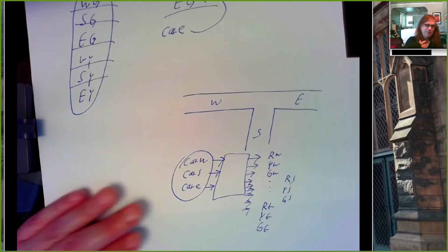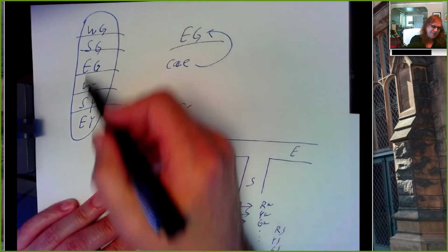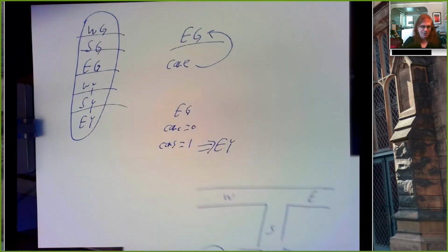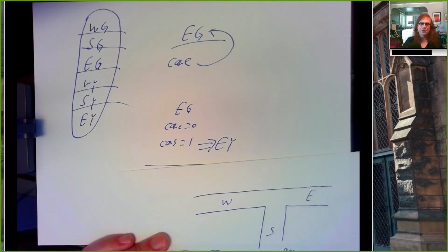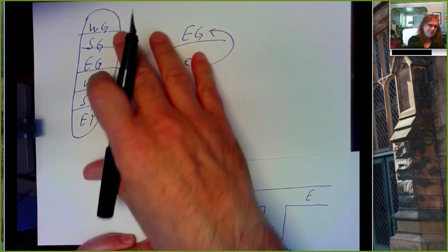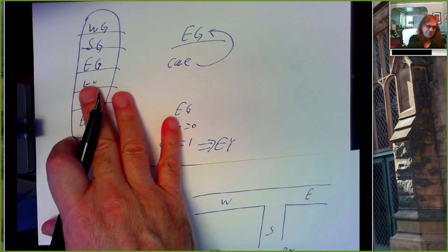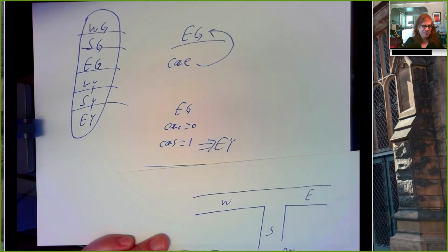And that's the part that you really need to design. For each of these 6 states, it's a few if statements if I write them like this, or a few arrows from circle to circle if I write it like a state diagram. But work this out on paper in whatever language you like, as pseudocode or pictures or whatever works for you, to try to understand how the system moves from one state to another.